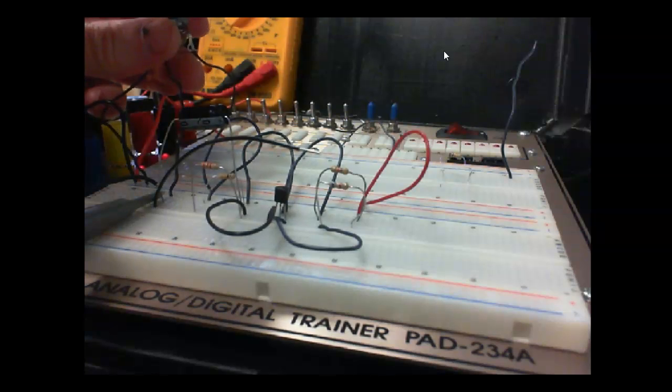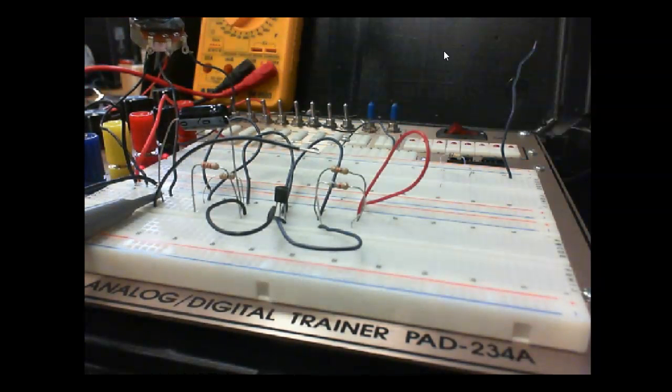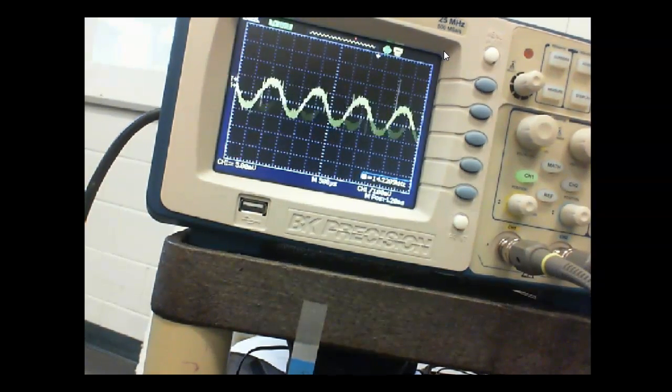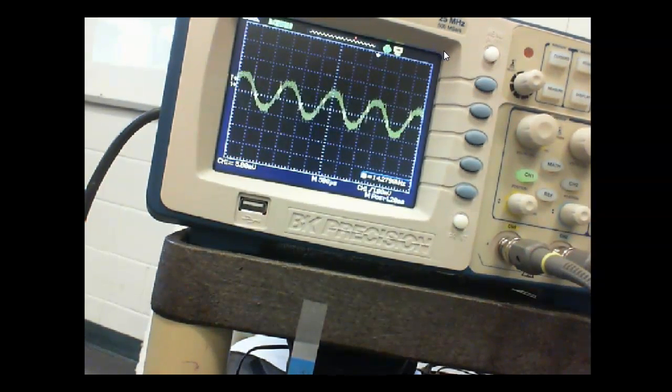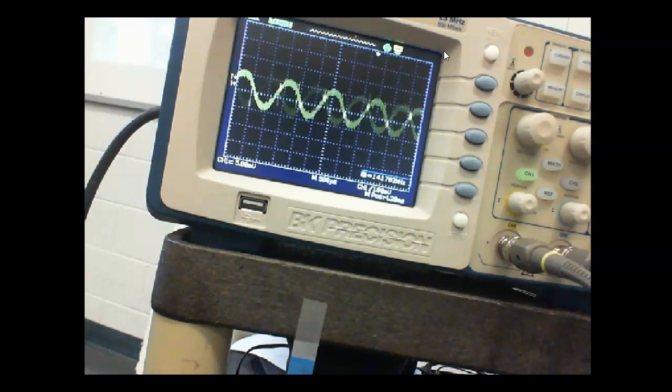And then I'll come up here and set it down to 10 millivolts, which would be roughly one division. I think we got a 0.5 on this. Let's see. Two divisions. And it's going to be hard for the scope to trigger on that because it's got so much garbage in it, right? But you can definitely see that's two divisions. I got it on 5 millivolts per division, and that's the best the scope can do, so that's 10 millivolts. Are we okay?